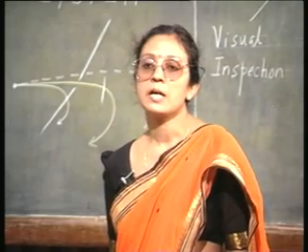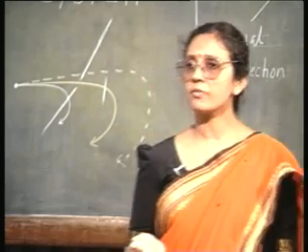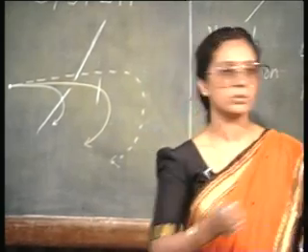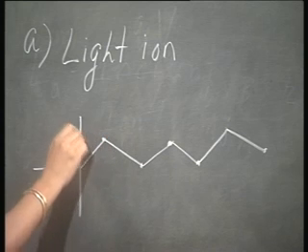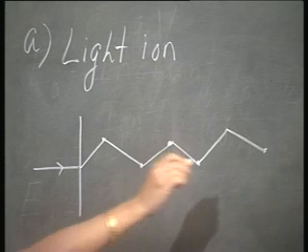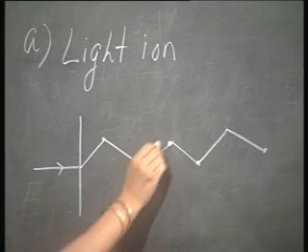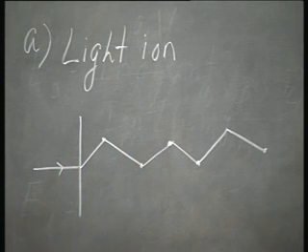Because the light ion is transferring a smaller amount of energy, it may not be sufficient to cause multiple dislocation. So, at every point I have just a small damage, but the incident ion is moving much deeper. Okay. So, I have relatively less damage, but a long narrow branch. This is what is going to happen in case of a light ion incident.